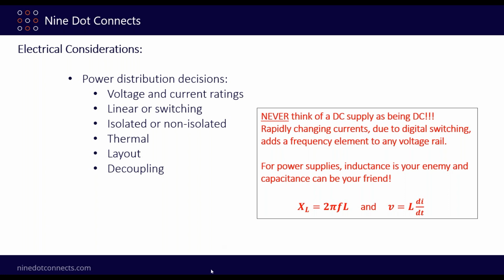And the other thing about decoupling, there's always an optimal decoupling, and there are papers out there everywhere. There are tools to figure it out. But the very nice thing about decoupling that you can decide early on is that if you have room for it, add extra decoupling, you can always take it off, okay? It doesn't hurt a design to take off a decoupling cap if you don't need it. And so after first proto, you can play around with decoupling and figure out what's best for you. And of course, that is if you have room. If you don't have room, then sorry. But that's why decoupling caps are very nice to work with.